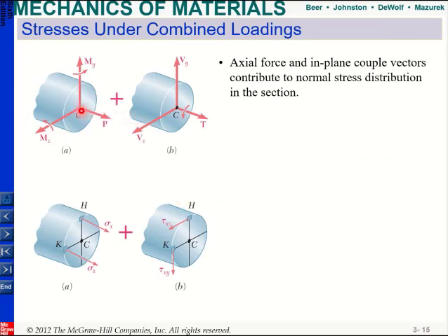So I know that, for example, in this case, if this is my x-axis, my normal force, my moment along y direction, and my moment along z direction, they create normal stresses. Okay, so again, your normal force, your moment along y, and your moment along z, they create normal stresses, which is shown there at, for example, these 2 points. Okay, and for example, if you have this normal force, I know that I can find my normal stress by P over A. But if you use My, it's important which point you look, because you will use My times z divided by Iy, and location is important.